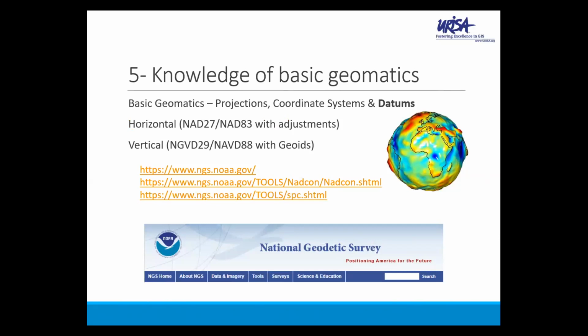And here again is something that one needs to be aware of. The Esri software has lots and lots of datums, some of which are not recognized by the NGS, NOAA. One of my favorites here in Florida is HARN. Everybody wants to use, for some reason, NAD 83 HARN. And HARN is just a minor alteration of NAD 83. The current datum that's recognized by NGS is NAD 83 with a 2011 adjustment.